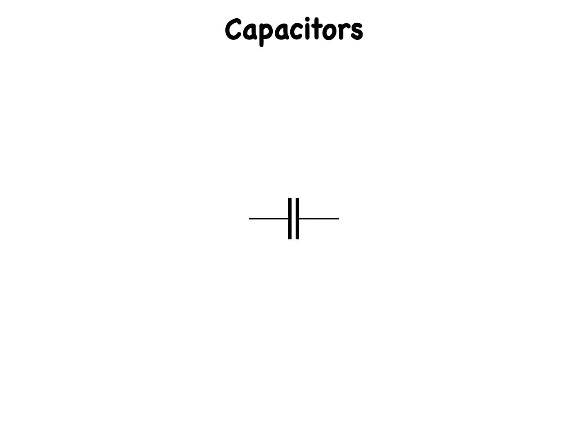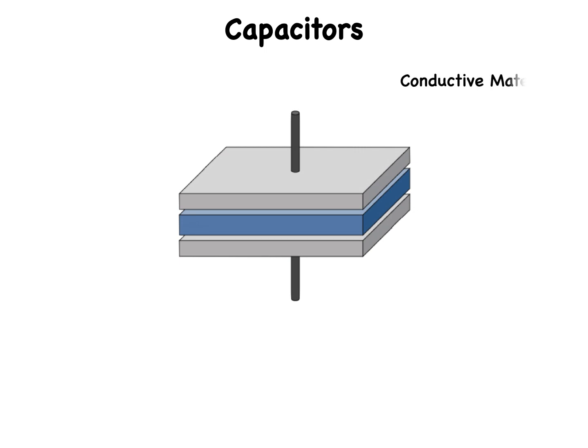The parenthesis side of a capacitor indicates the lead that should go to electrical ground, or to the circuit point more nearly connected to electrical ground. Unless the symbol includes a polarity sign, it indicates a non-polarized capacitor, which might be made from metal plates surrounding ceramic, mica, glass, paper, or other solid non-conducting material, and, in some cases, air or a vacuum. The material designation indicates the insulation, technically known as a dielectric, that separates the 2 major parts of the component. Physically, a typical fixed-value capacitor comprises 2 tiny sheets of conductive material close to each other but kept electrically separated by the dielectric layer.